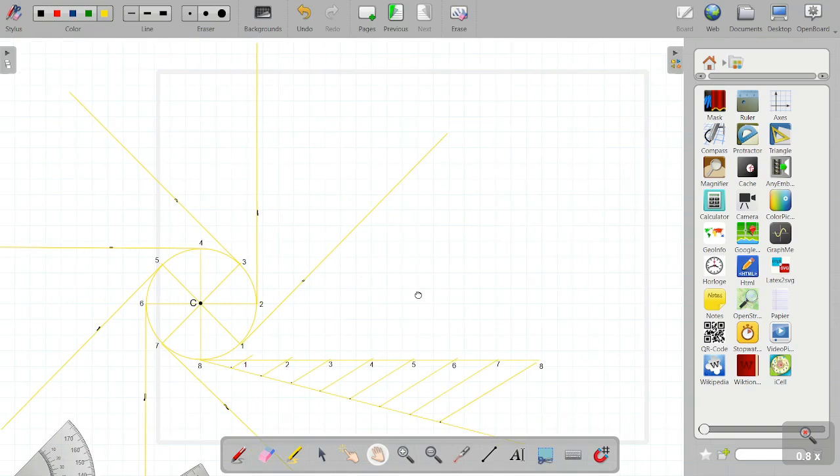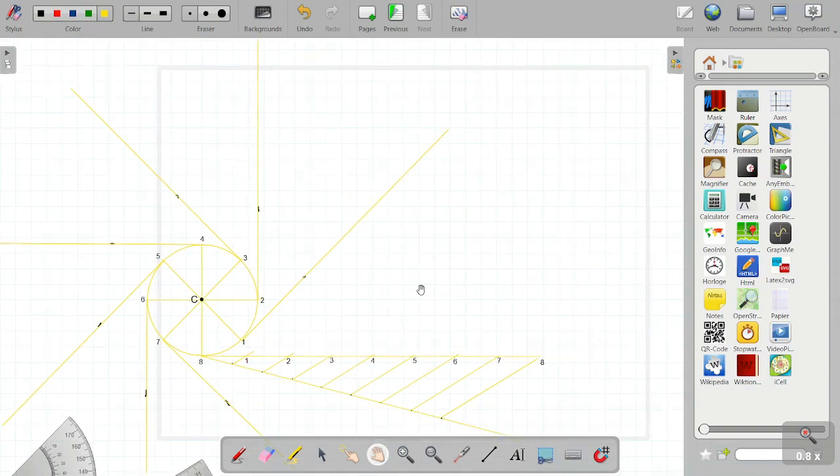So till this step, as I mentioned in the previous question also, the process for drawing an involute of a circle will remain same. Now, after this, we need to check if there is any length of the thread given. In the first question which I solved on involute of a circle, no length of the string was given, so we considered that the length of the string will be equal to perimeter of the circle.